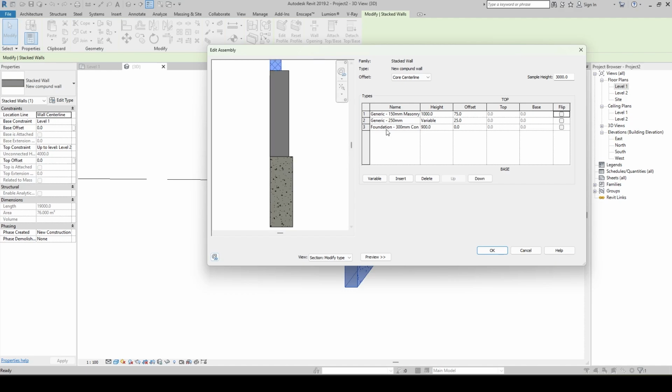For example, if you want to take one side of the compound wall, all the different walls in a single line, you can use the offset concept. That means the foundation I have taken as constant, then the generic wall I have taken as 300 minus 250. So how much is left? I'm left with 50 mm. So 50 mm on either side you are left with spaces. So I have taken one side left space as 50 mm, that means 25 plus 25. This is taken as the left side. So the offset has been the same line. That means it has aligned in the same concept, which is applicable to the top. That's how I use the offset concept.